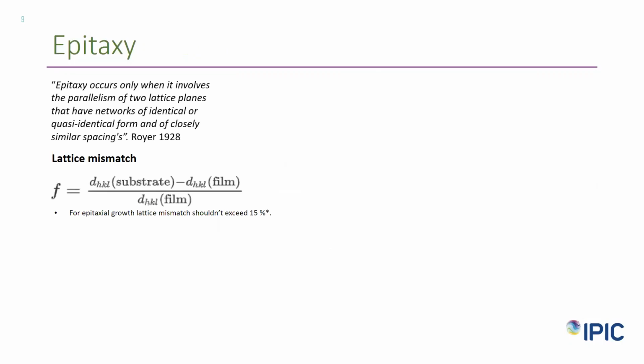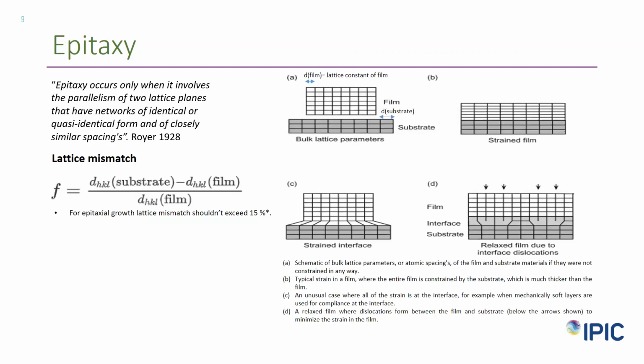So now we will take a lead and see what epitaxy is. In the simplest aspect, I will say epitaxy is like arrangement on. I will again refer to the same video which I showed you earlier. So we require a base material and we grow on top of that. So it's more like following the same crystal. And in this figure, you can see that a substrate material or lattice is used to grow a film on top of that. You can see the lattice constant of the film and the substrate.